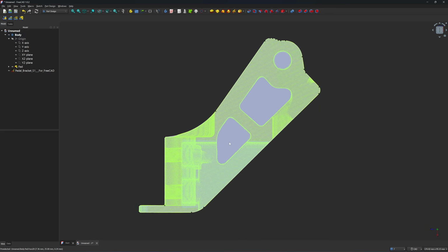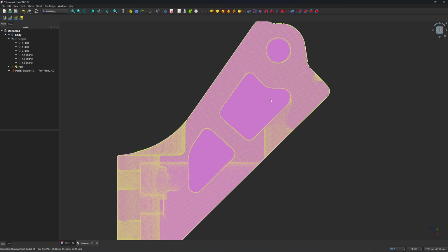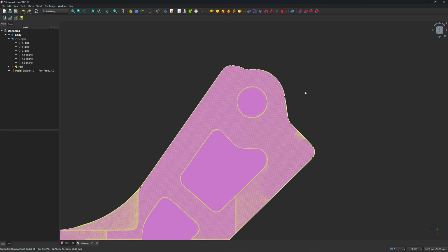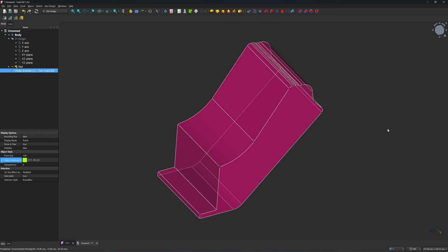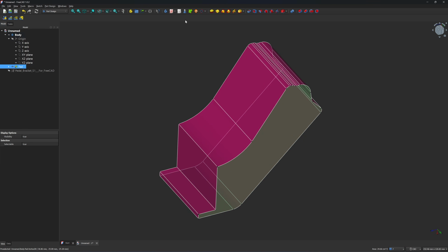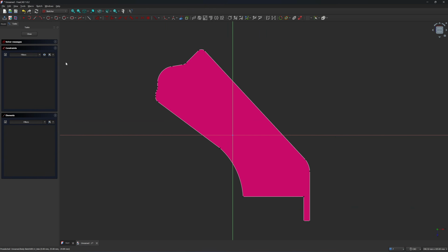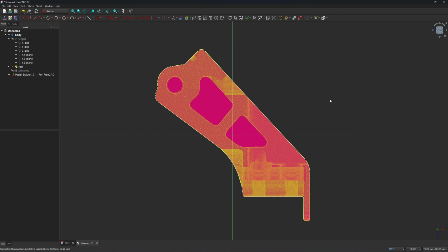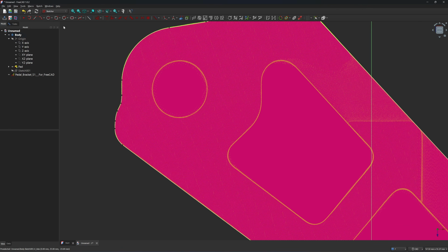You see these two pockets and the hole. They were made by extrusion. So I'm going to trace the profiles of the two pockets here and one circle. I'm going to click on the plane here. If it's difficult for you to click on the plane, you should turn off the point cloud first. Click on the plane, click on sketch. So the sketch will be created on this plane. And next, I'm going to turn the point cloud back on and start tracing the geometry.